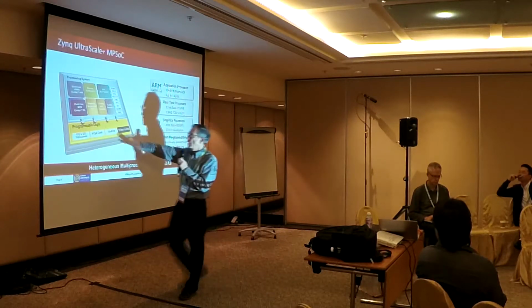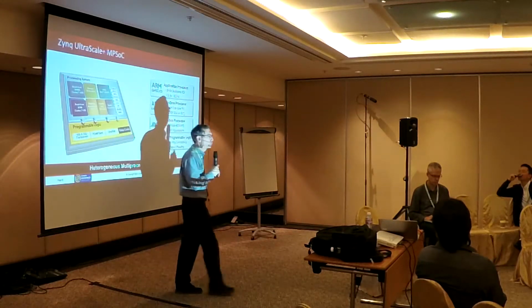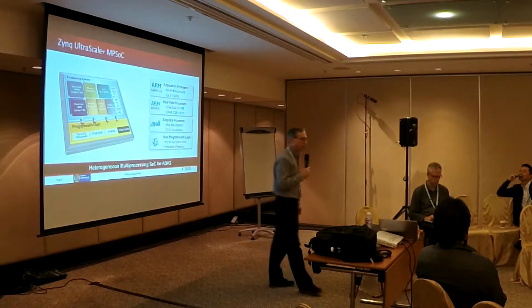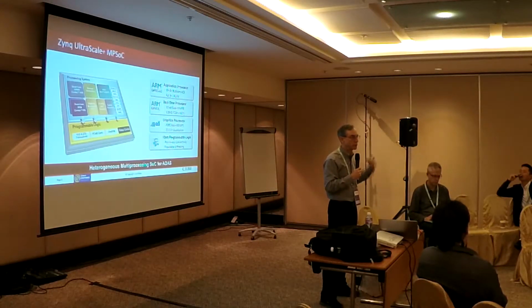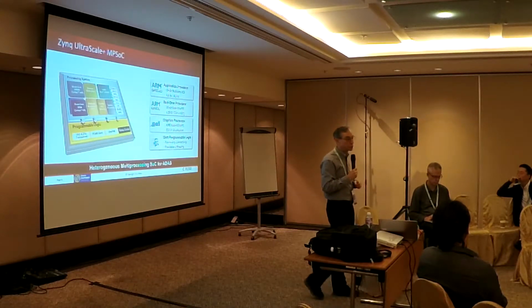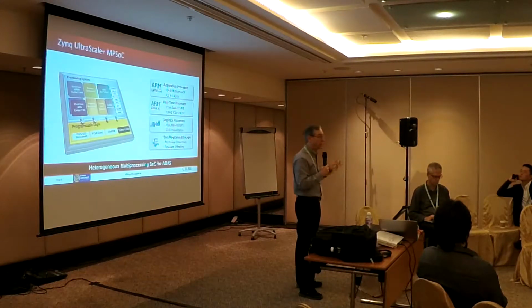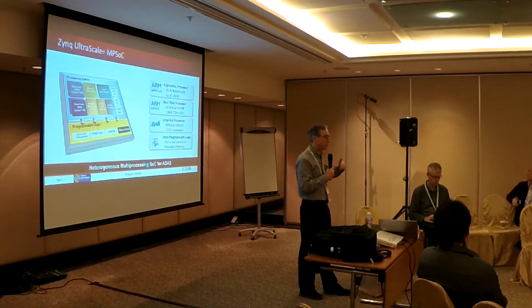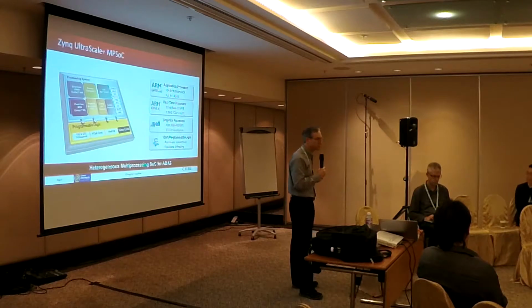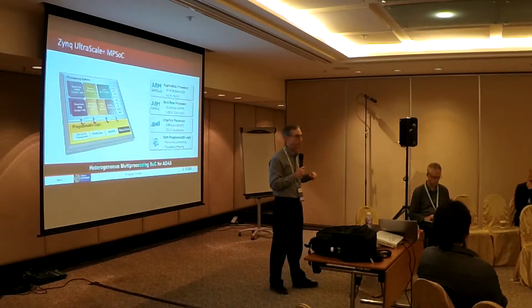Speaking of which, we have something called a platform management unit, a triple redundant processor. It's used for a variety of different functions. All our power management firmware sits on the platform management unit, along with various error handlers. In fact, that's probably where you want to put all your error handlers that might come in from another system, so that you have the most robust portion of the system handling system level errors. And if you're doing functional safety applications, you might want to put your most critical code there.